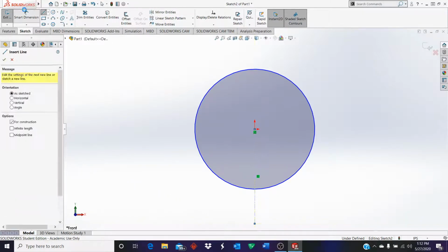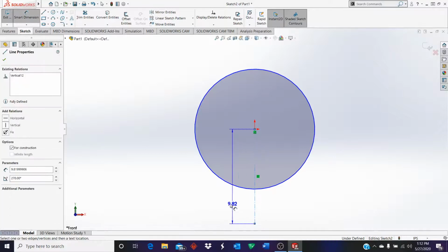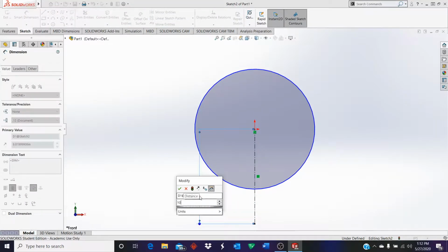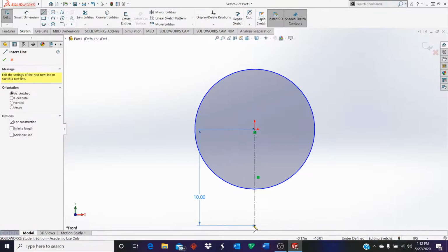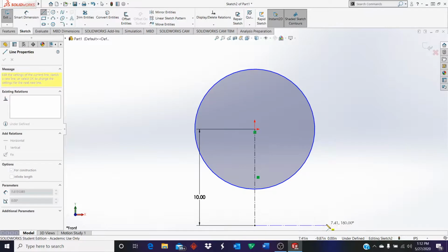So I want it to be 10 inches down. So now I'll go back, click my center line, I'll expand however I want, because this honestly doesn't matter. Your center line is just used to help you construct and get to certain aspects without intruding measurements.